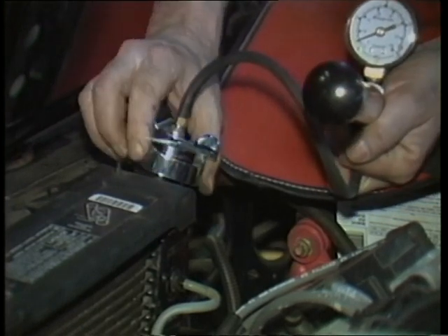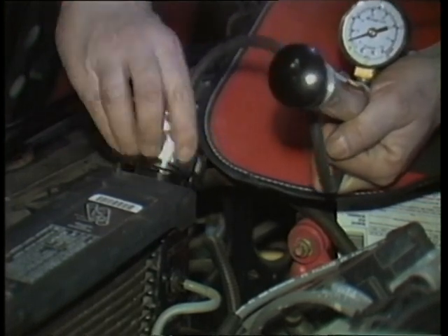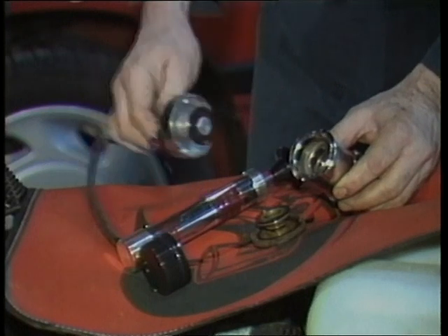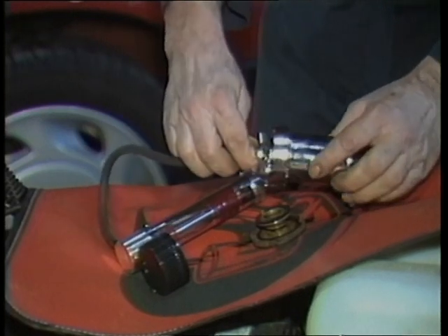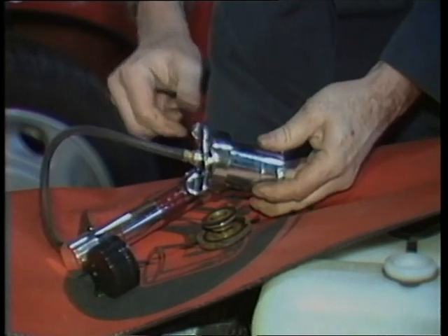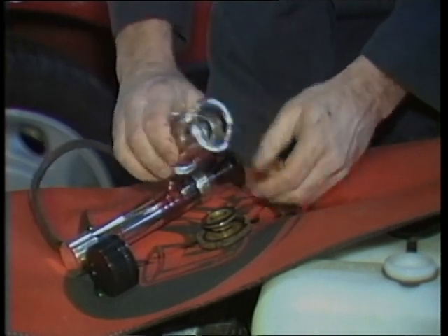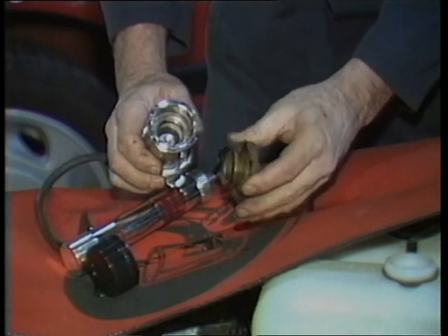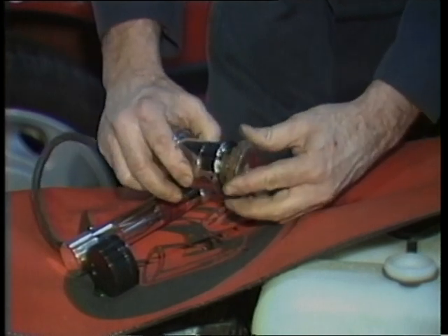With a tester handy, you should also use it to check the condition of the radiator cap. Mount the adapter onto the tester, then fit the old radiator cap onto the adapter. Make sure you have a tight fit at the adapter so you can get an accurate test of cap condition.